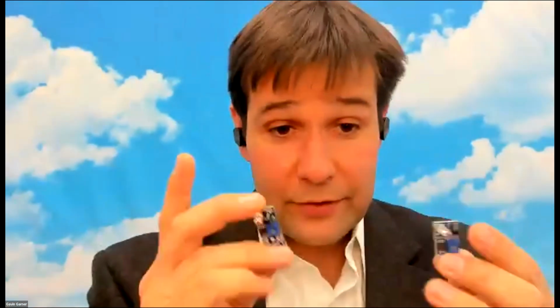So we actually use 2 of these to do a quadrature encoder, with these offset on the same acrylic disc, and one of the smart pins decodes the quadrature no problem, and it turns this into a servo motor, which is remarkable. And again, the students are working on that right now in my class. So I like these sensors, and I'm trying to think of new novel things I've been experimenting with.